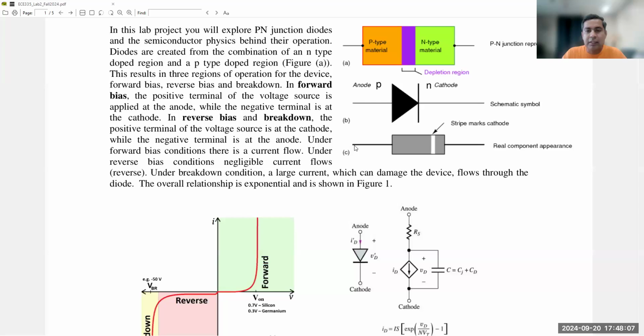So when you connect this device with a power source and other components, if the anode is connected to the positive polarity terminal of the power source, then this is called a forward bias connection, meaning the depletion region will decrease because of the extra added electric potential on this device, and then the electrons will start to flow after the voltage across it crosses this V on point.